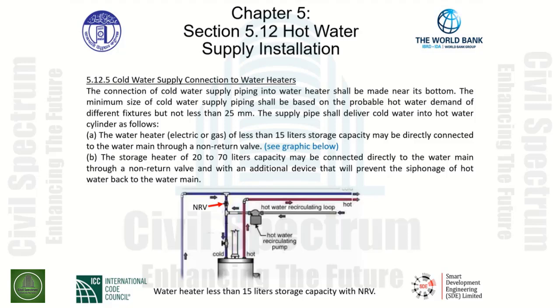A, the water heater, either electric or gas, of less than 15 liters storage capacity may be directly connected to the water main through a non-return valve.